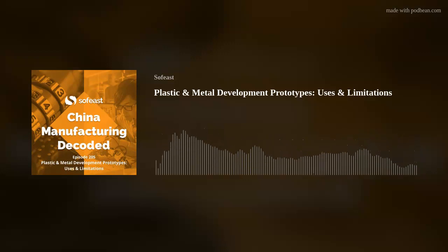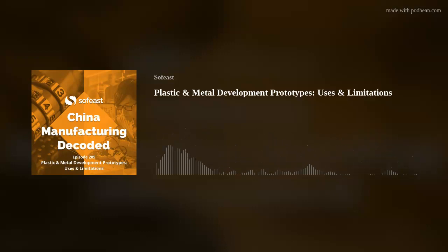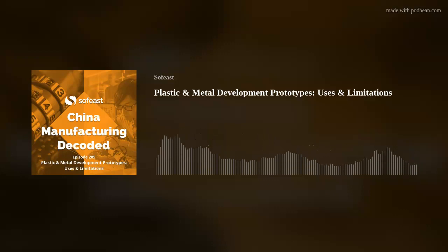The waste from plastic injection molding, you've got all the little runners and things like that. They're basically little tiny plastic parts, right? And they're in a big bin next to the machine. And those can actually be reground and used again as plastic to go into injection molding. Obviously, there's certain ways to do it. You don't just use only that. It would probably be mixed with virgin plastic. And so it's quite a circular process, actually, injection molding. It doesn't create a lot of waste. Correct. Yes. You don't normally just use 100% regrind. The percentage is lower, but you're right.